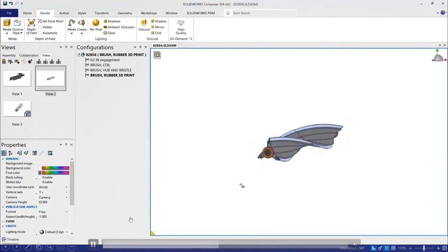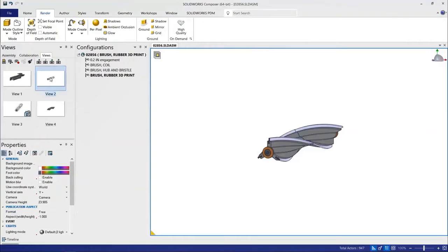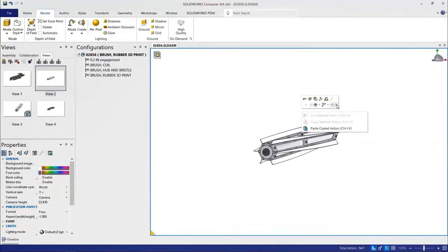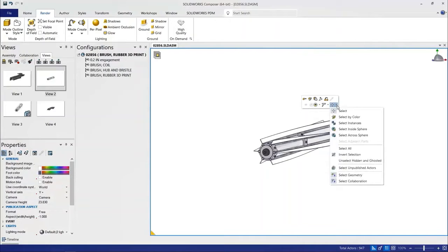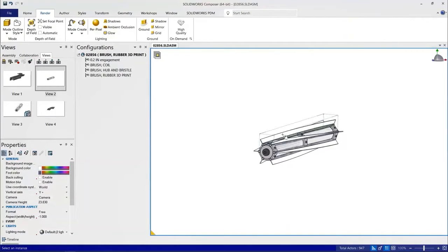So now we're going to grab the twisted configuration here of the turbine roller assembly, and we'll show that as an item for a view to create in the other documentation. Might be nice to have an explode view here, and one of the selection options we now have is the ability to select all the instances, in this case of the pattern blades.